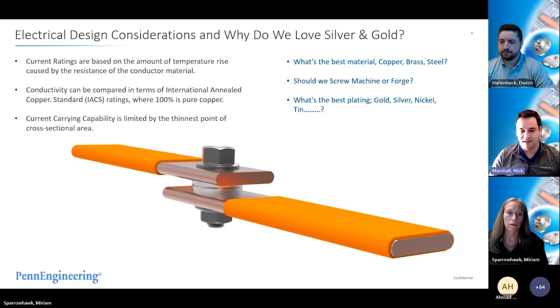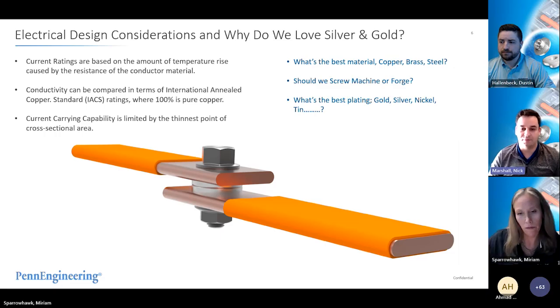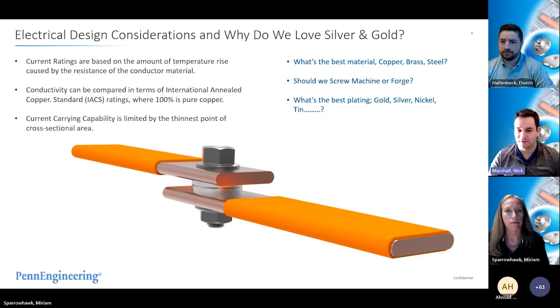And so with the eConnect contact bushing, one of the benefits that we've found is we can manipulate which plating we apply to this bushing, and we can put it into any standard bus bar depending on what the needs are for the application. If you have a very high service life, very critical junction, it's probably more effective to go with the silver plating where you're going to get that tarnish resistance and that ultra low contact resistance.